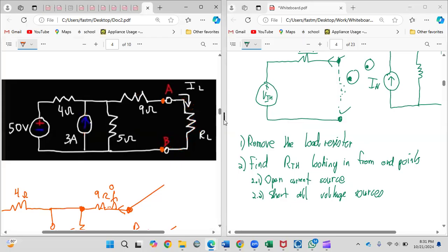So basically it's equivalent to you plucking out the resistor, taking a multimeter, measuring the two terminals and getting the voltage across it. Because remember the idea: you're trying to break apart the complicated circuit into one resistor, which models the resistance of the rest of the circuit, which I don't care about, and I want a voltage at the endpoints here, which would not change, constant. Once I close the circuit by putting in my RL, I know it will be 10 no matter what.